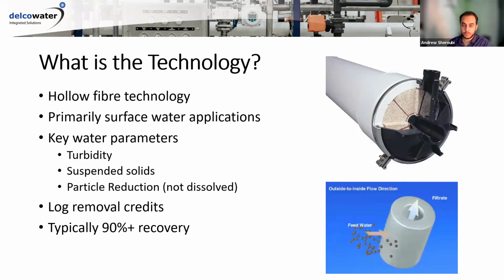The pore size of most UF technologies is 0.01 micron. So that is smaller than most, as I said, most bacteria and viruses. So extremely effective at removing those things.